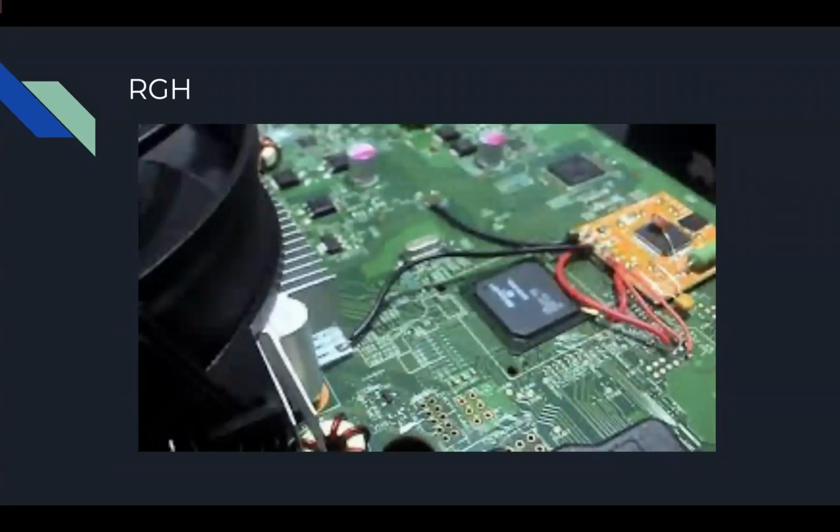So when it's verifying the kernel, what that essentially boils down to in assembly instructions is: run all these RSA encryptions, and then branch if this register is 0, depending on whether it's a successfully verified kernel or not. Well, they found out that they were able to slow the clock down and then pulse the CPU reset pin.